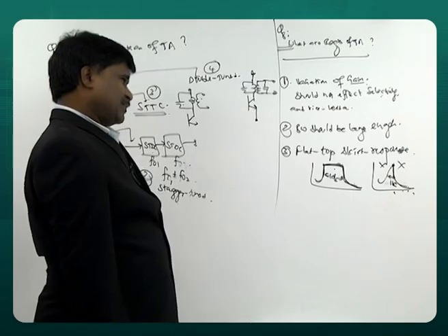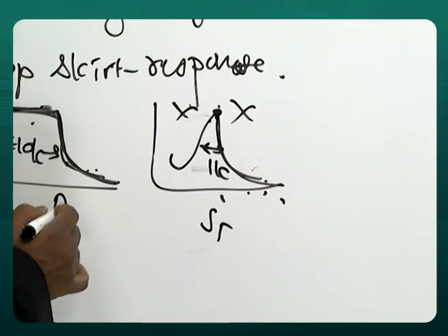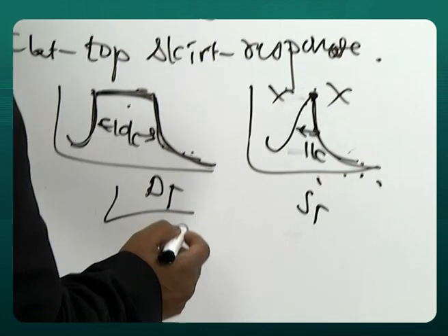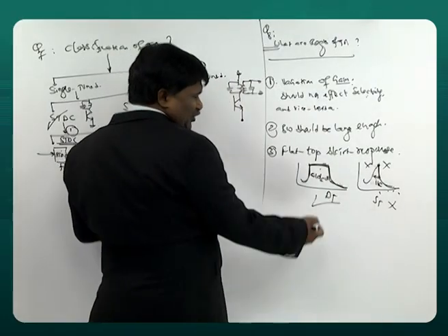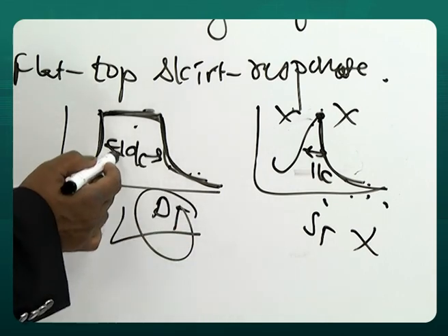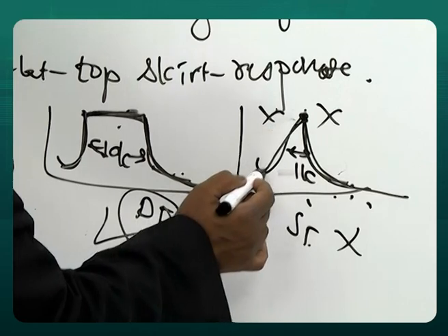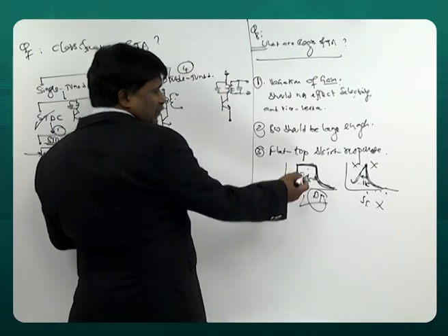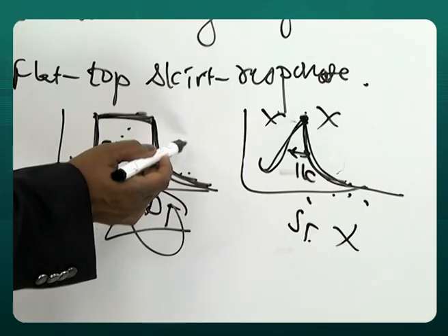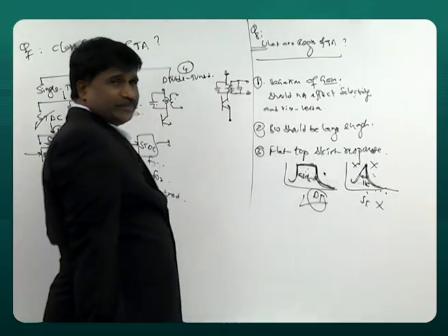In fact, all this is single tune, and this is double tune. That's why double tune is better than single tune. Though the bandwidth of double tune is more, it is better because it is suddenly falling. Slowly falling is bad, but suddenly falling is good. Because this is a pass band, eliminating it should be fast elimination. This is slow elimination. That's not good.